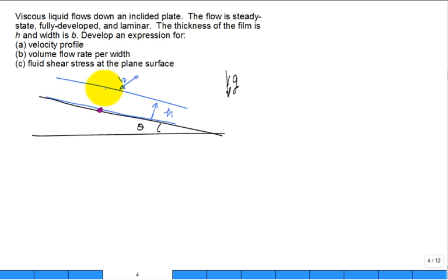At the top. And so what we do is we introduce a slightly changed coordinate system, x and y, so that things are aligned where the flow is only in the x direction, not in the x and y, but only in that rotated coordinate system x direction. And we're looking for the velocity in the x, which we use the symbol u for, lowercase u. And that u is not a function of x, but it's a function of y. That's a lot to swallow. But that's what we're looking for.